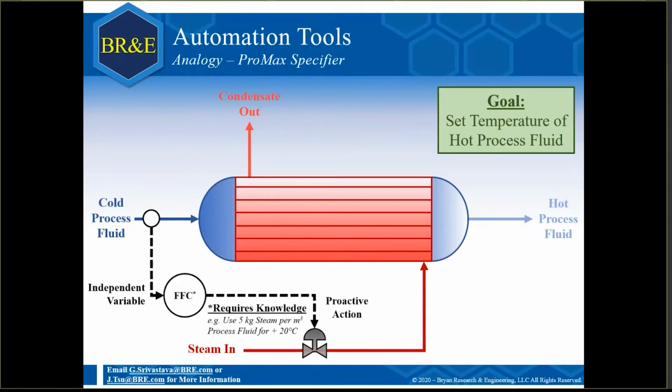A feed-forward controller then uses some information to create proactive action. So this one is ahead of it: before the fluid even starts getting heated up, it already creates the action for you. So how does it do it? Instead of using intelligent trial and error until you hit 0 error, you need some sort of knowledge of the system. And this coalesces in some mathematical relationship.